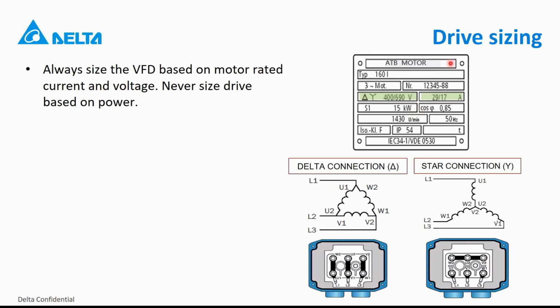Okay, so it's very important to keep this in mind. So never size the drive based on power, always size it based on output current.